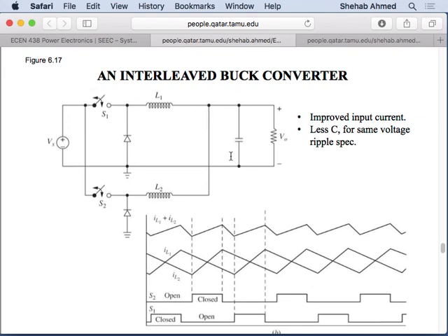Okay. The other topic we want to address a little bit here is, if you have a certain load current that you would like to achieve that has a certain amount of ripple, you will design your inductor for that ripple content, right? How do you design an inductor? We said we look at the voltage waveform across the inductor. The area under that is the flux linkage, the energy we're storing in the form of flux linkage around the inductor. If that area under the voltage curve decreases, I'm able to choose a smaller inductor. If it increases, I would require a larger inductor, right?